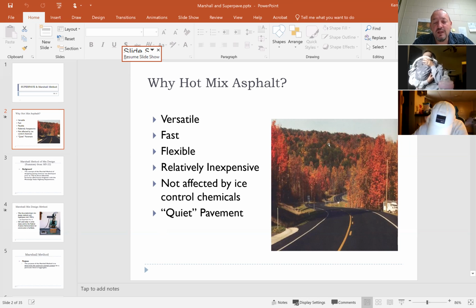And then they would probably talk about the ride quality. You don't see many rigid pavements anymore that you drive on, but if you do go over a section of road with a rigid pavement, they're typically jointed about every 30 feet. So as you're riding, you go boom, boom, boom, boom like that. Whereas an asphaltic pavement that is placed well would be very smooth and quiet. So that might be a good selling point for them.